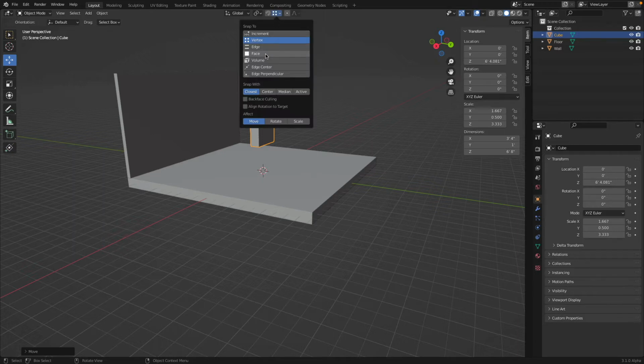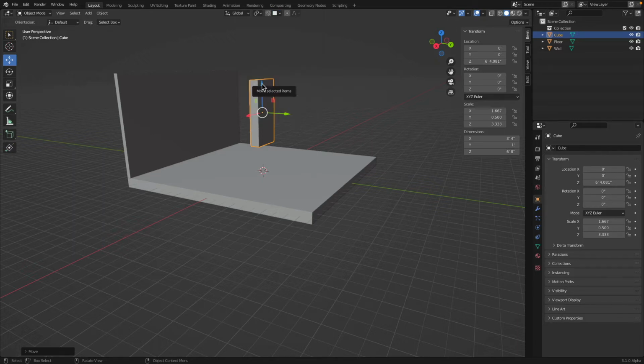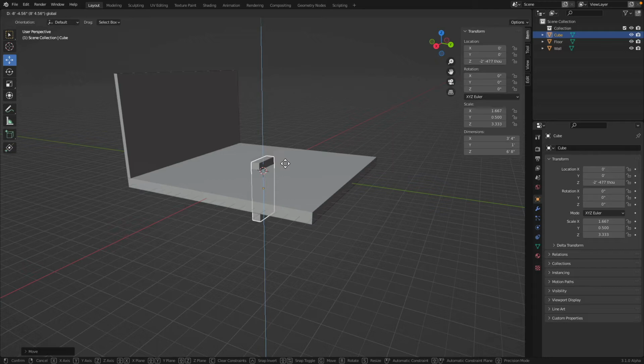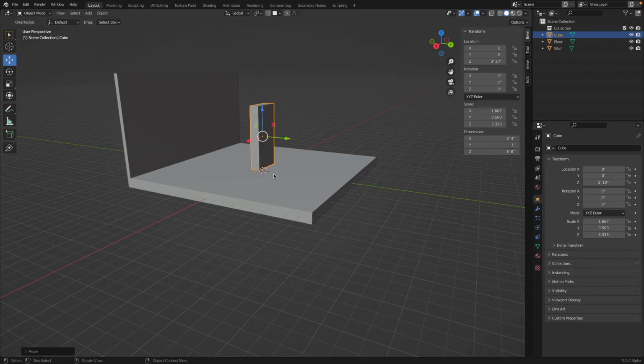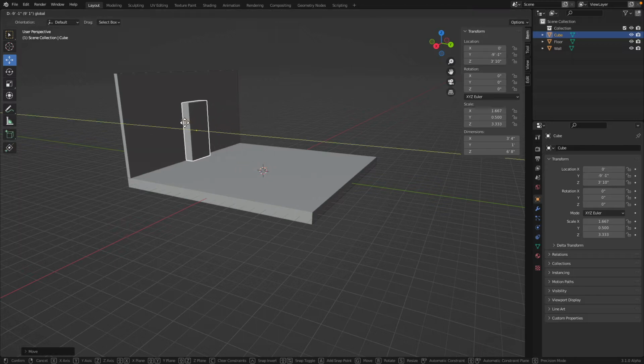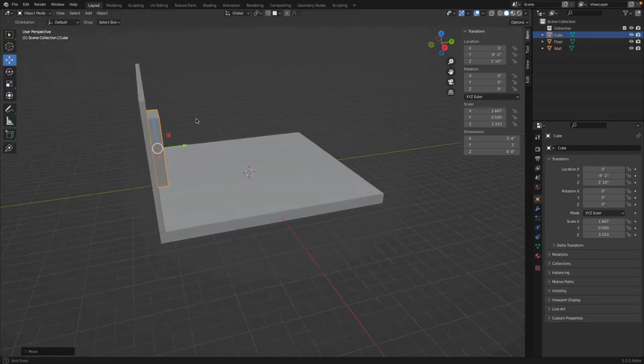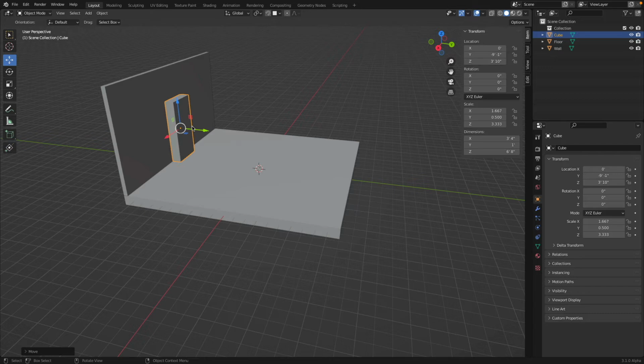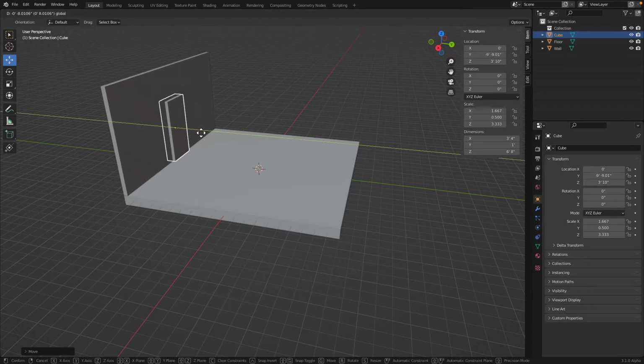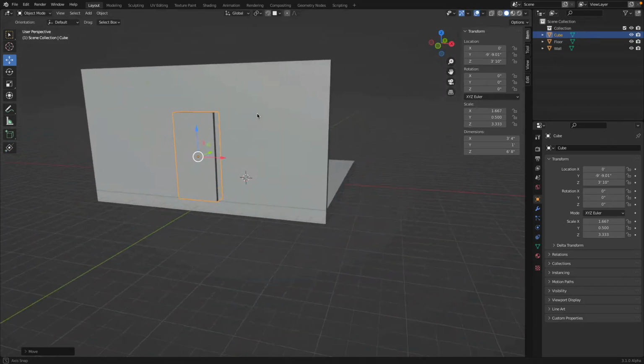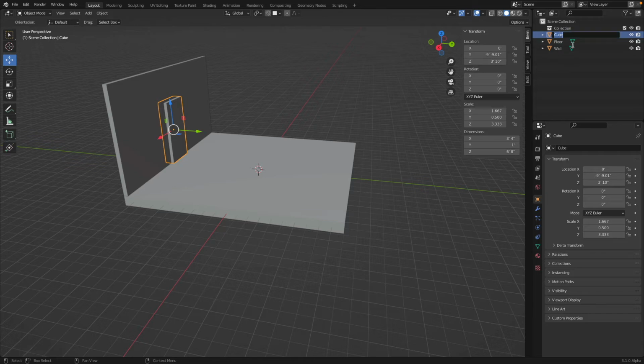Then I will actually go to face. So you see what happens when I move this one down and I hold the control key. You see how the lower face lines up to this face. When I bring this over and hold control, it lines up onto that face. Beautiful. Let's slide this one in like this. Very good. And we can call this door. And now this I will drag into here. Double click and I call this maybe Boolean.